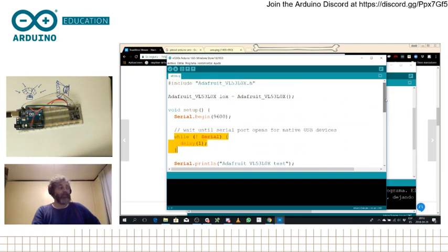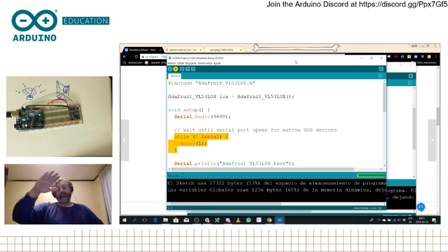So this is what is called a time of flight sensor. It's the same thing as the ultrasound, but using different technology. So we just run this, and if it works nice, we will see how when we move our hands up and down on the sensor, it will be ranging the distance to the hand. And then we can mix both codes together and have an XYZ sensor. And that's what you can see in the example from Bitcraze and Hackster, because what they do in the example is detect that you're moving your mouse XY and then pressing a button, touching on the air.